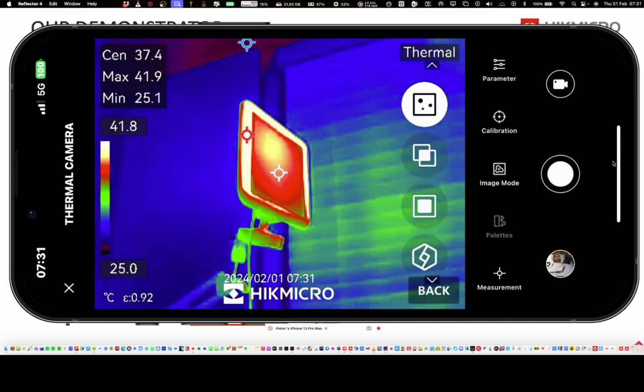One needs to get into a proper angle to stop that infrared radiation that is actually reflected from the panel. A very important point when you're troubleshooting a panel.